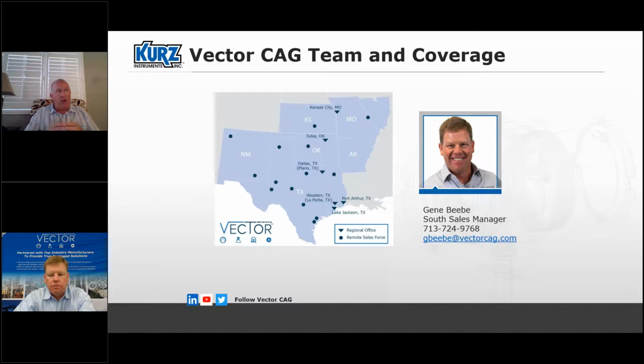So constant power type thermal anemometers, their response times are typically in minutes, whereas constant temperature thermal anemometers, the response times are in seconds. So constant power anemometers are typically only used in monitoring applications for maybe stack flow where you're not using it for control, or they use a lot of them in flow switch applications where they just want to know level in a tank and things like that. Okay.